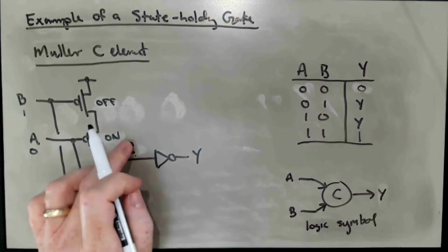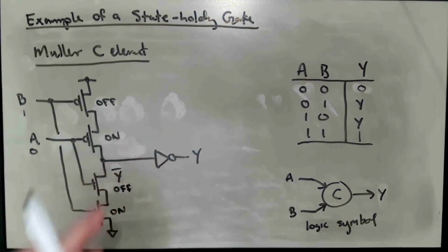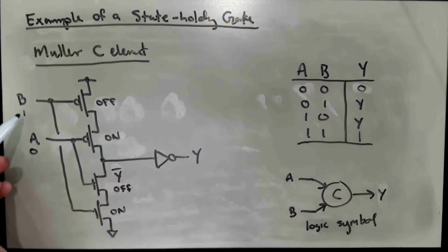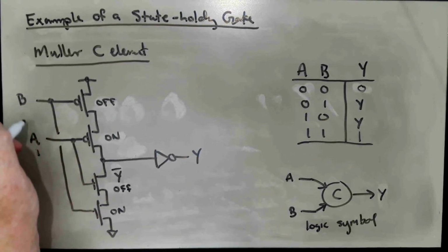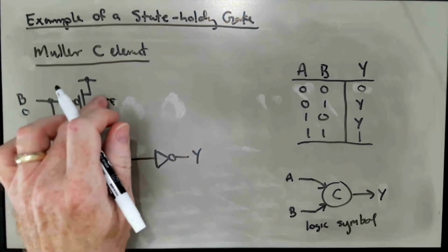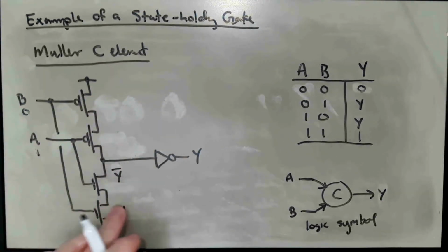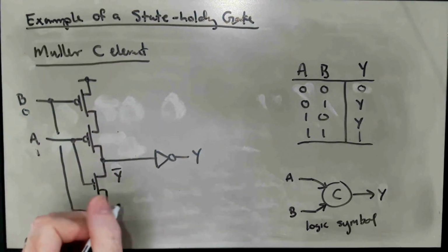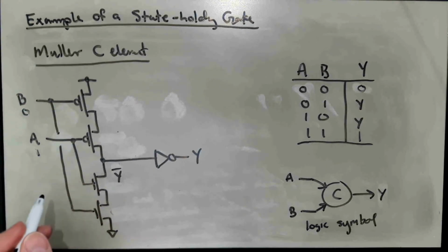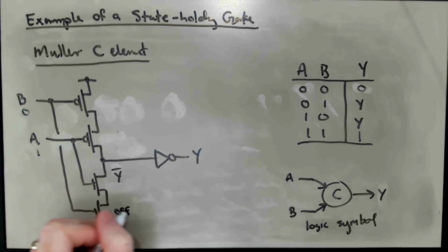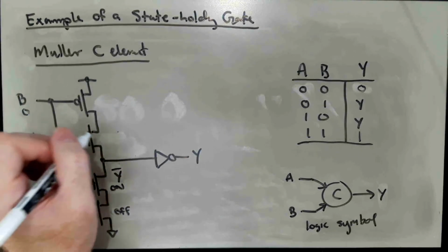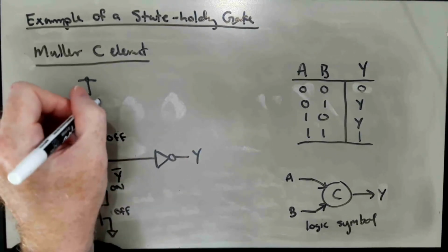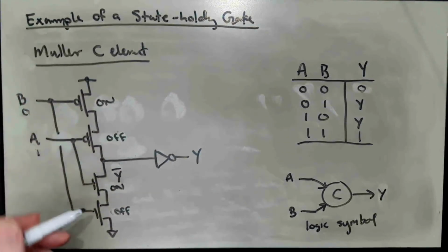Now this particular implementation of the gate, I should say that if we flip this to the 1, 0 state, these transistors sort of flip their state from off to on, right? So this transistor is now off, this one is on, this one is off and on, but still both networks are cut off.